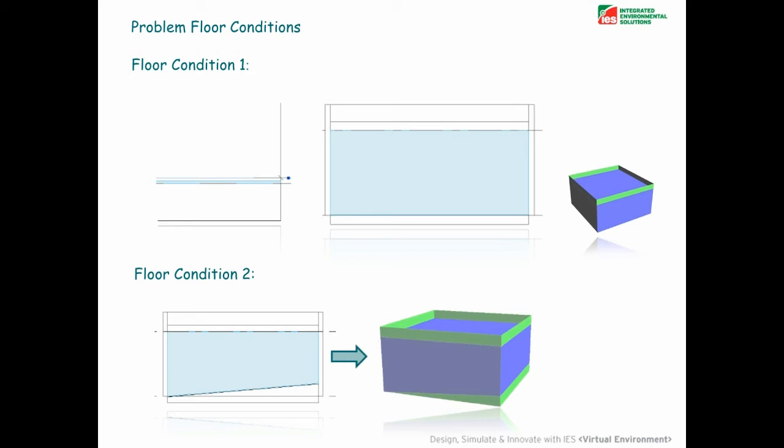The condition 2 there at the bottom is one to mention. It's just where you maybe got an access ramp in a multi-storey building. Maybe it's 10 stories, 7 floors as an access ramp. Again, we would just untick the room bounding element of the access ramp.